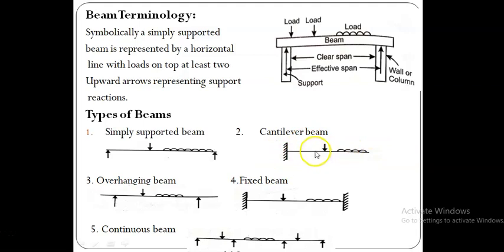So as far as this case is concerned, this beam is subjected only to vertical forces, and therefore it is producing only the vertical reaction. Suppose this beam is carrying any horizontal forces, then it is producing horizontal reactions at its end. Okay, so whatever forces are acting on this beam, the whole reactions are produced by only this fixed support, because the other end doesn't have any supports. That is called a cantilever beam. So a cantilever beam can simply be said to be a horizontal member with one end fixed and the other end free.